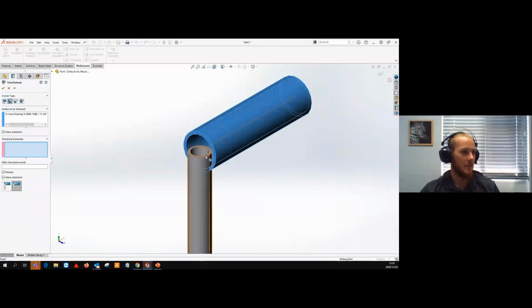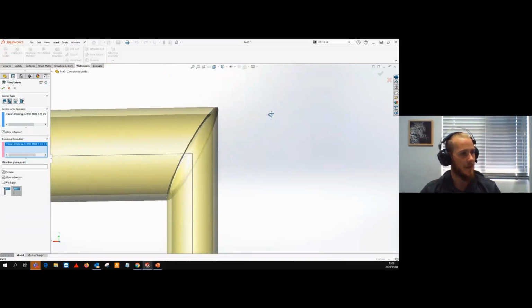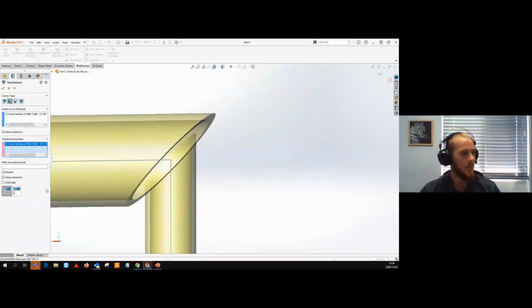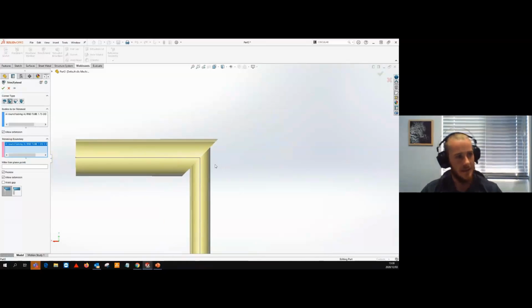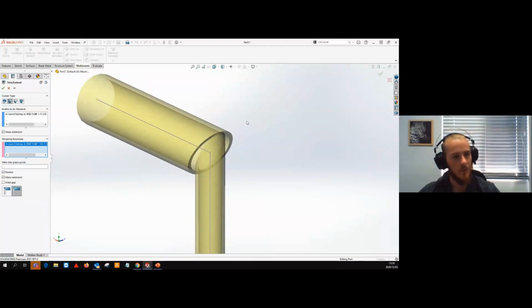The bodies to be trimmed for this afternoon will be those two, and you guys will automatically see the software taking care of that blend for me. It recommends, obviously, the full flush miter. I'll quickly show you guys what the other one looks like when we deal with the equal option. There we can think of it as cutting at a 45-degree angle, and then the flush option, or full flush miter, looks something like that. You can clearly see what the software is doing in the background to line those profiles up as well as possible, even though the diameters are worlds apart.